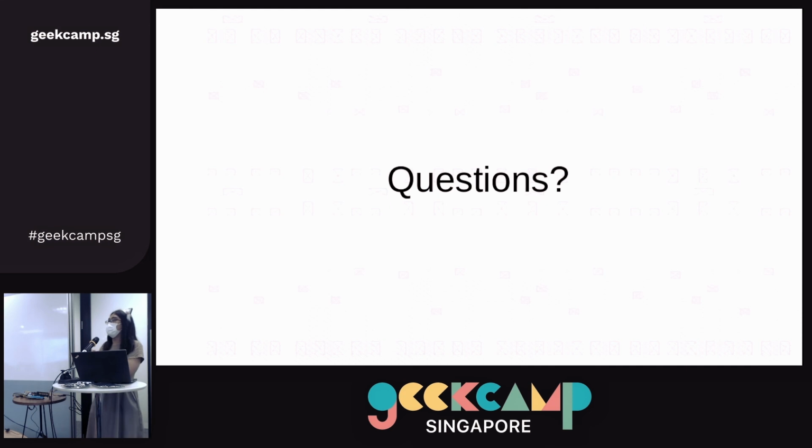Yes. To do that, let's say we look at an off-the-shelf chip. As I said on the previous slide, even if a chip is tampered with at the dopant level, even with a scanning electron microscope it can be very difficult to detect, because with doping level attacks you don't actually change the physical structure of the chip itself, only the electrical characteristics of the transistors on the chip. So how then can you know that the chip has been tampered with? It's very difficult and very expensive. Some of these processes are actually destructive. In order to figure out how that chip was fabricated, you actually destroy the chip itself, and that's not accessible for most end users.